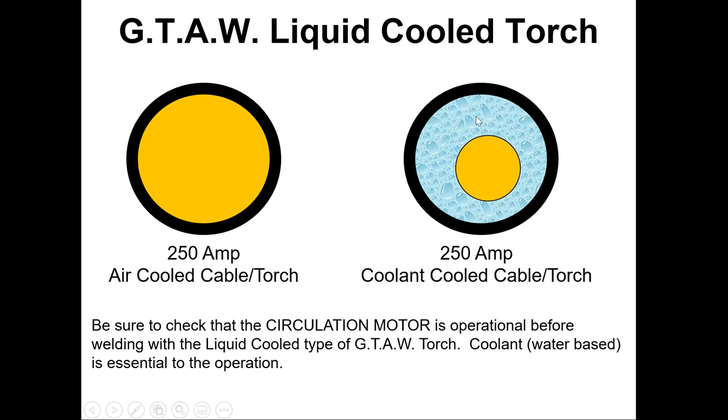Here's the problem with this. If this water is interrupted at all, this cable gets hot fast, and it just starts everything burning and melting, and the water starts coming out, and then the arcing starts to happen as a result of the short circuit because the water is everywhere. It's kind of a problem. So you have to be cautious of that.